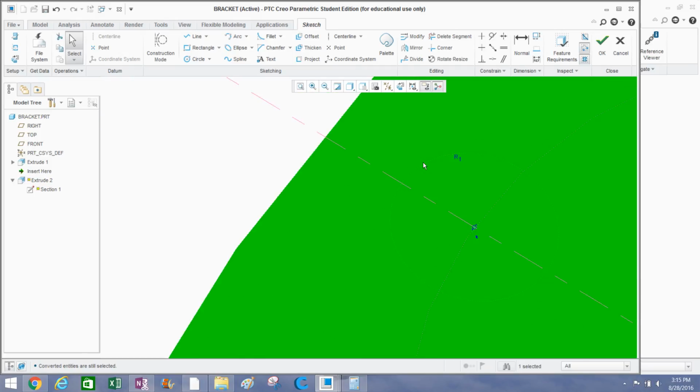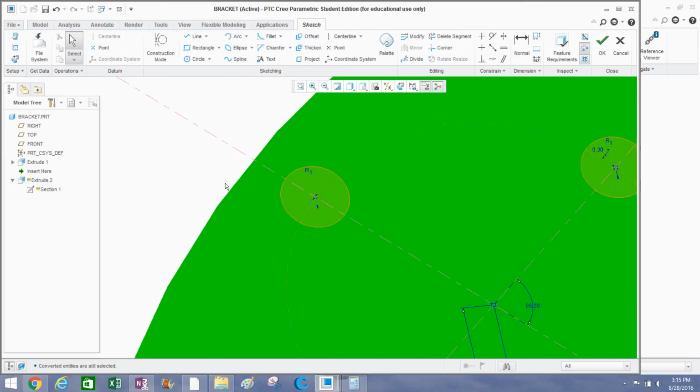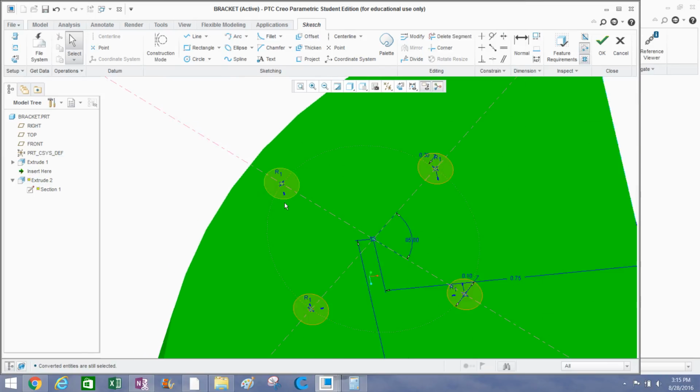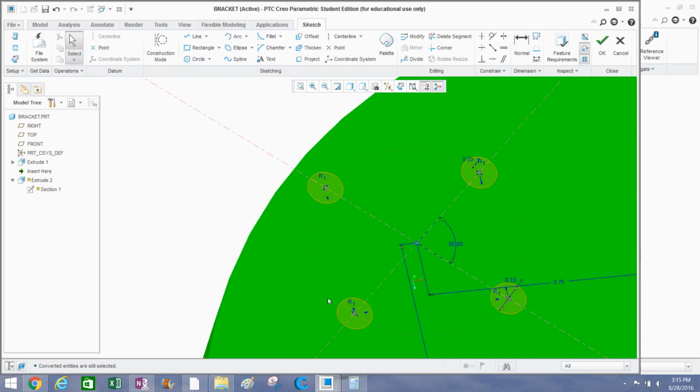And now it's impossible to see, but there is your construction lines right there. And you should be able to unselect this guy, change it to geometry, and now it's back to where it was before. So basically, if you use a construction line, it'll allow you to do nifty things like this, where I located the circle on a certain diameter circle. The circular hole cuts rather on the circle, and I made this construction line, and these circles are the only things that are actually being extruded.